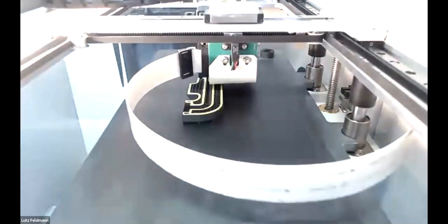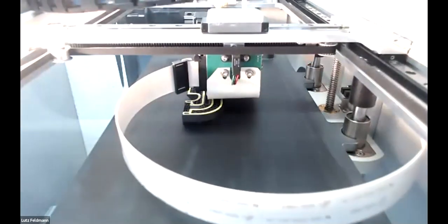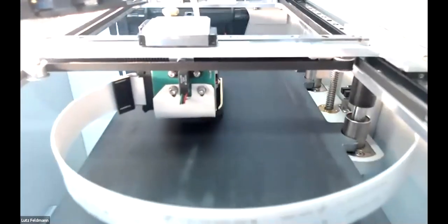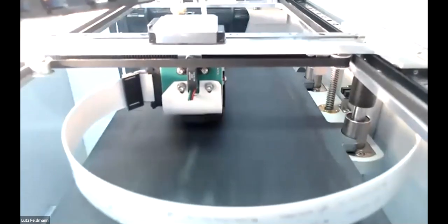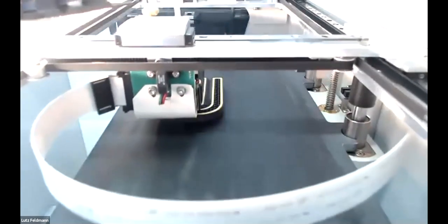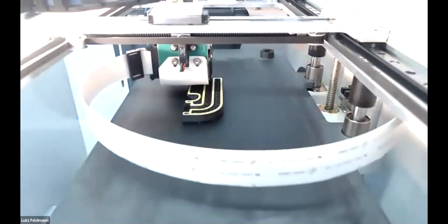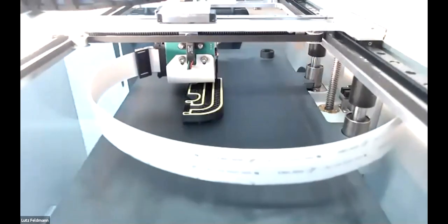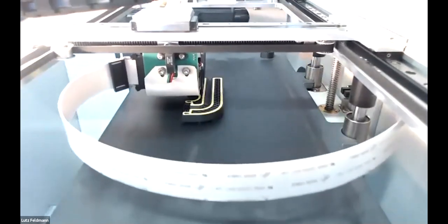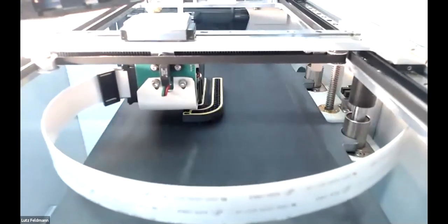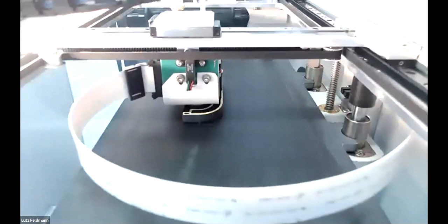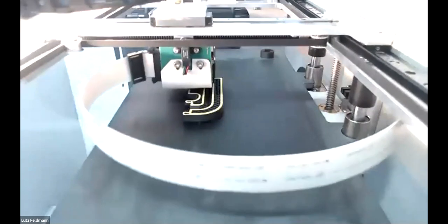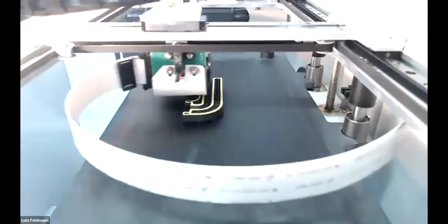The yellow lines are actually Kevlar. So we basically have 2 nozzles in this printer. One nozzle is doing the plastic, the nylon. And the second nozzle is actually laying down a constant string of Kevlar fiber, and it's cutting. There is a little cutter in this nozzle, and it's cutting it and starting with the next one. So the end result is actually a super strong part, which is of incomparable strength to what you may see in other plastics and with chopped fibers alone.